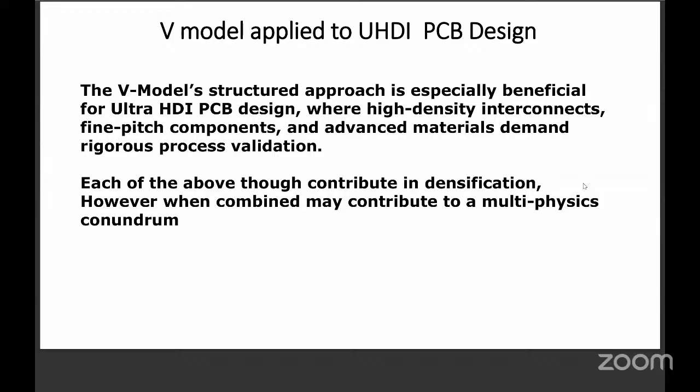V model applied to Ultra HDI PCB design. Why? I could have explained this in the previous slide, but I wanted to highlight it here. The V model's structured approach is especially beneficial for Ultra HDI, where high density interconnects, fine pitch components, and advanced materials, considered separately, demand rigorous process validation, because each of them contributes to densification, but when they come together as a cocktail, they create a very volatile mix.